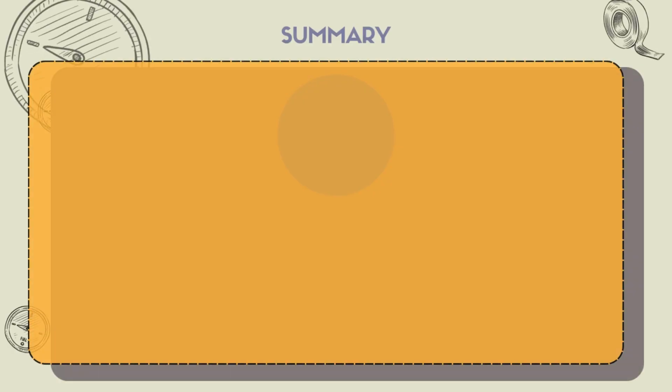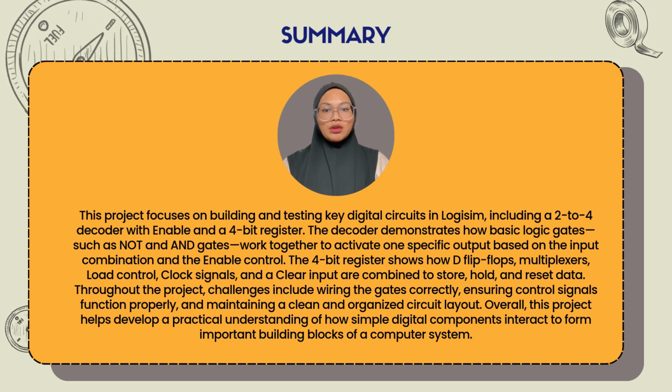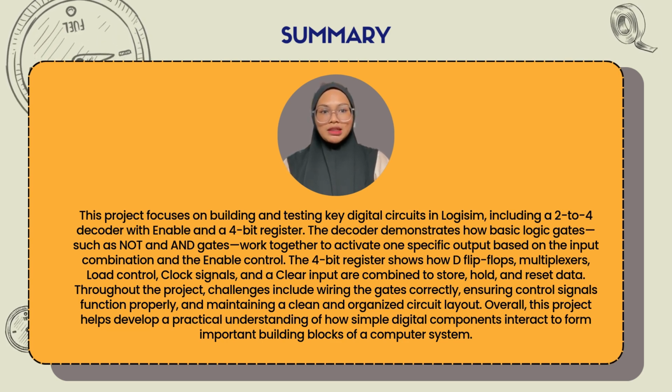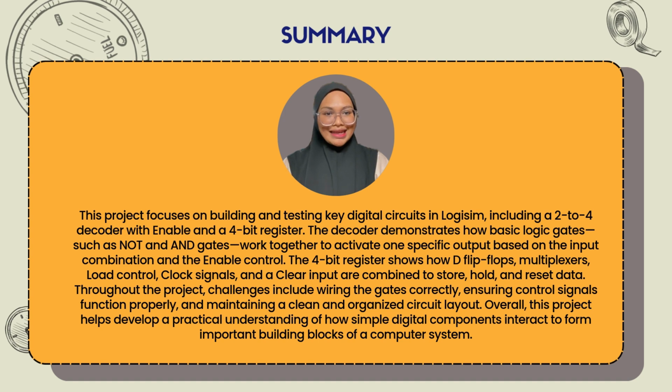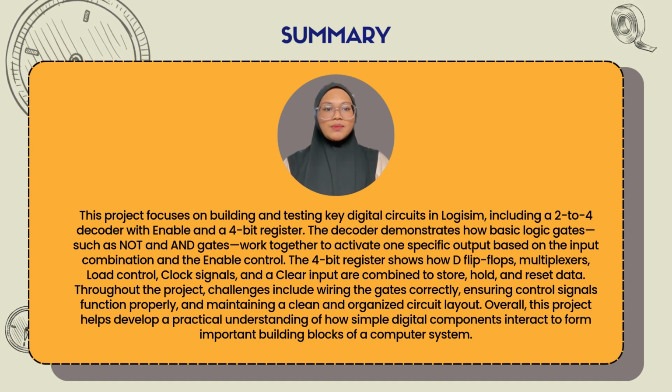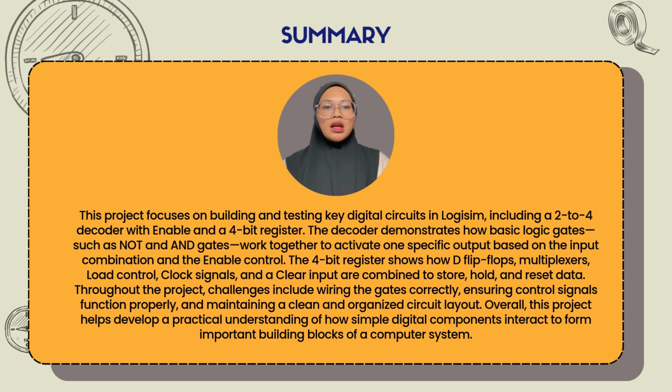So in summary, this project focuses on building and testing key digital circuits in Logisim, including a 2-to-4 decoder with enable and a 4-bit register. The decoder demonstrates how basic logic gates such as NOT and AND gates work together to activate one specific output based on the input combination and the enable control.